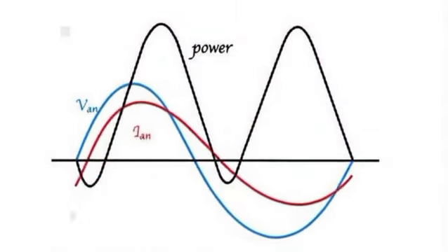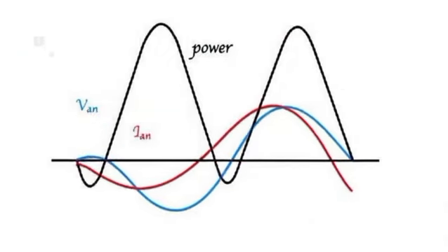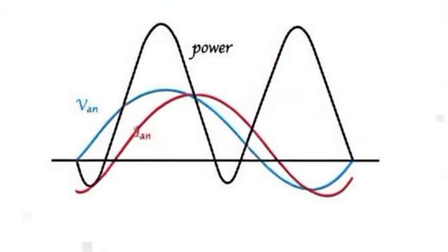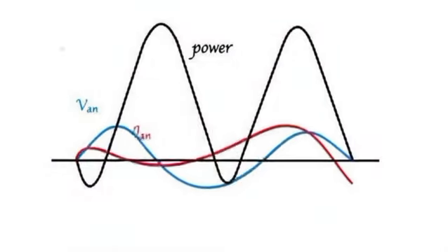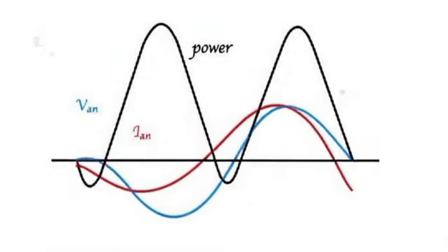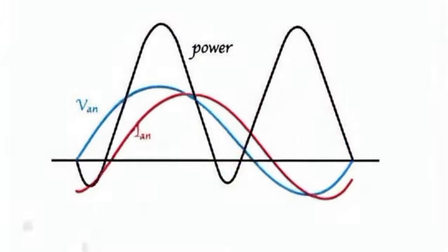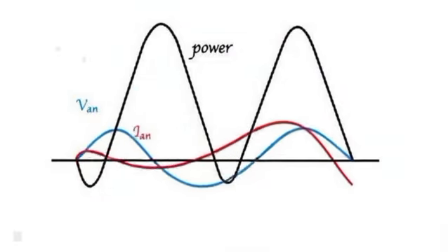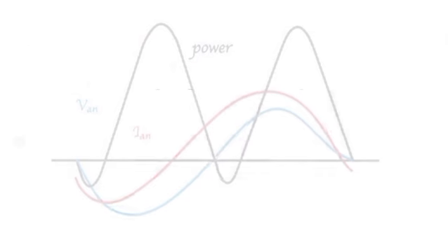Consider the wave shapes of voltage supplied to the AC circuit and the current through the purely capacitive load. As it is clear from the above figure, current I encounters the zero crossings of the time axis some phase earlier than that of voltage V. This is referred to as leading power factor. The figure below represents the leading power factor triangle.